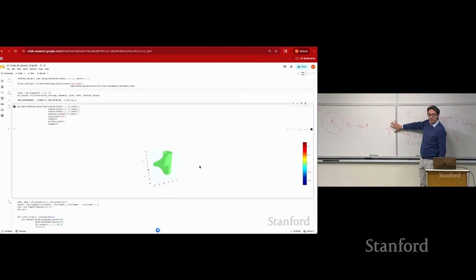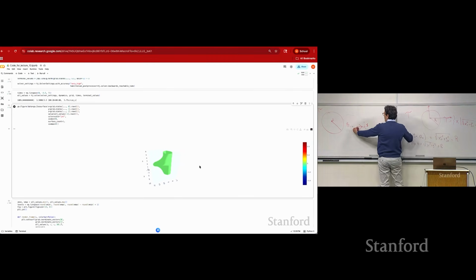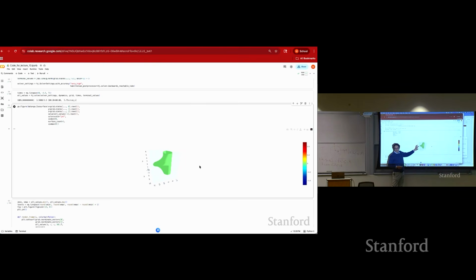Does it make sense? So this is just saying something obvious, right? That if the two aircraft are on a collision course, you need to have more lateral separation. That's what this blob here is saying. But it's kind of nice that we computed it from first principles, and we know exactly, for each possible value of the relative heading, by how much you want to ensure lateral separation, also taking into account longitudinal separation.